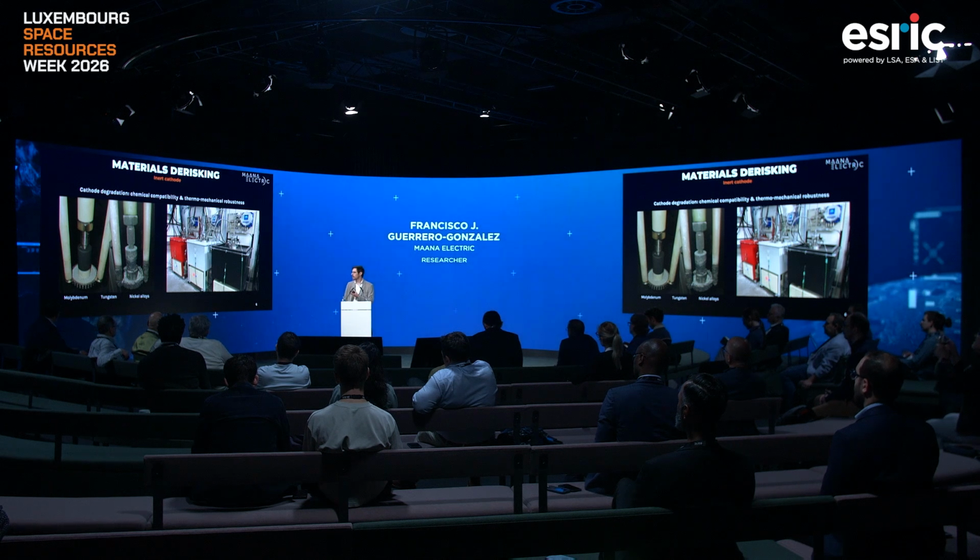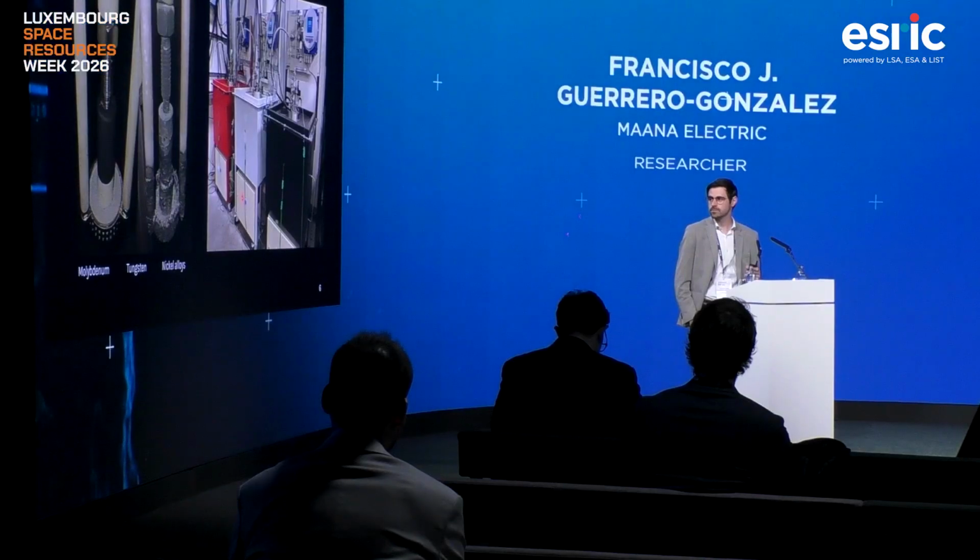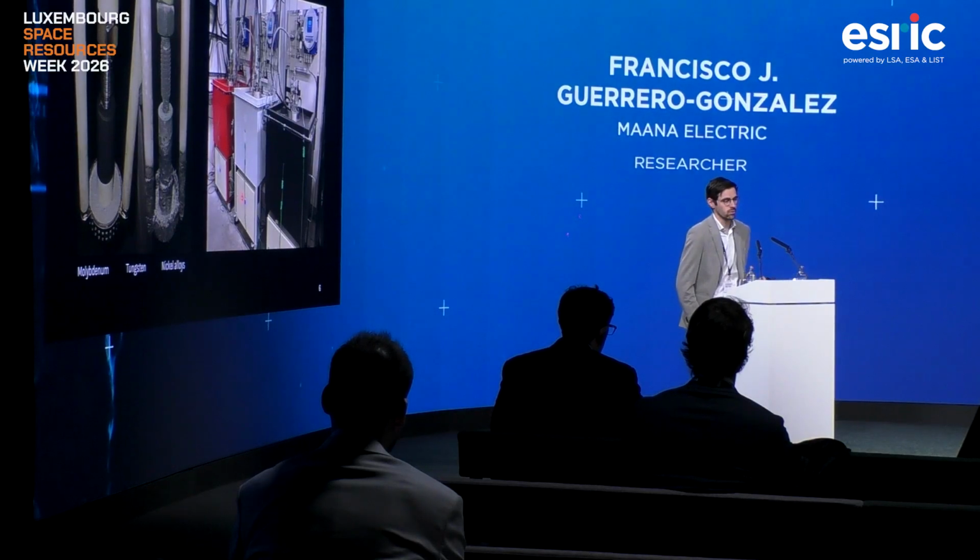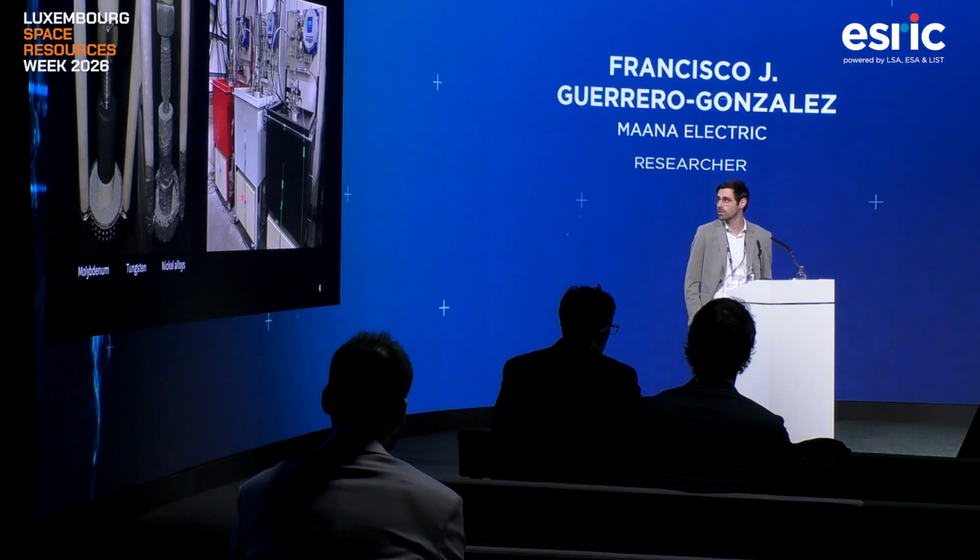They are brittle. We had already experienced similar behaviors with ceramic materials. That's why we have seen that one of the most promising materials is nickel alloys. Of course, there's a bit more material transfer between the reduced regolith and the nickel alloy components. But that's something that, at least for a demonstration mission, we have learned to live with.